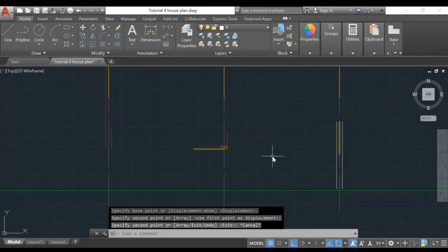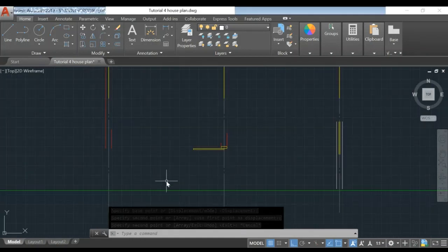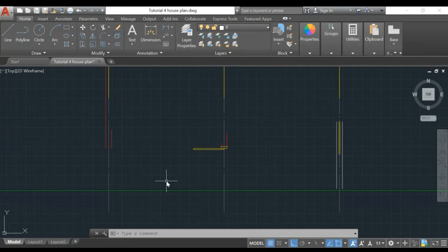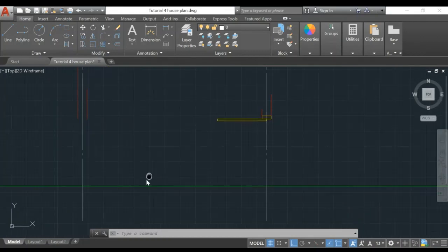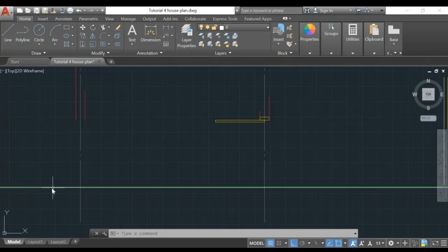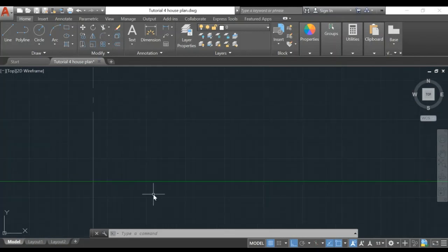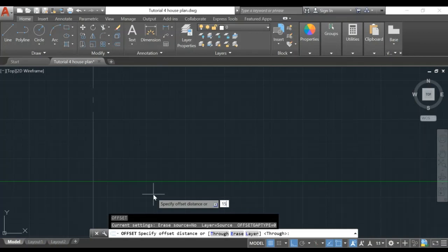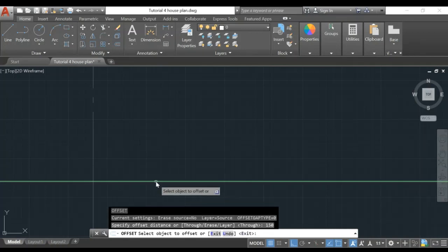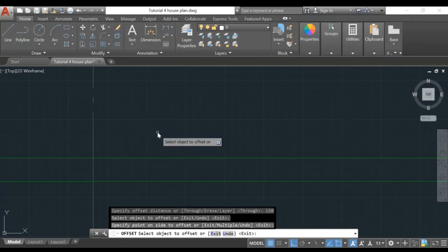But as I mentioned just now, once we have this, what we need to do is get to know or do research on the height, right? So this is a house. Usually the house, if it's a ground house, should have a raised floor, usually about 150. Sometimes you probably require steps, right? So in this case, I'm going to raise the floor of the house here about 150. It's 150. Okay.